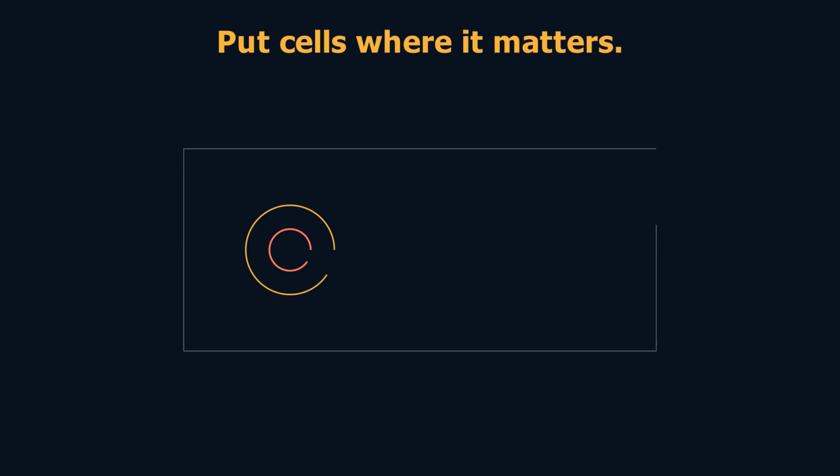You don't mesh all that open air evenly, that would be a waste. Straight from the grading lesson in episode 3, cluster cells where the flow is interesting. Refine a region hugging the body, that's where the boundary layer lives and where drag is set. Remember Y+ from last episode: those near-wall cells decide whether your drag is trustworthy. And refine the wake, the disturbed region trailing behind. Coarse cells there smear out the very vortices you often care about. Everywhere else, big cheap cells are fine.